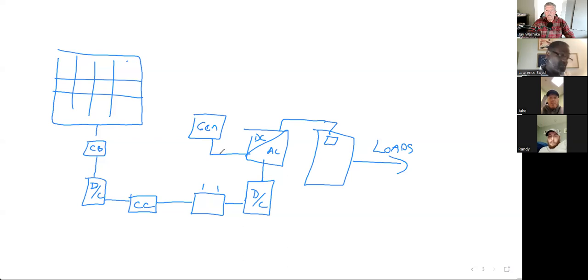Very common, very normal. You don't have to have the generator in this case, but a lot of people do, if it's your only home. Now, what I wanted to reinforce, other than walking through all the different parts, is when I turn on a load, how does the power flow? If I draw a line halfway through the battery, the solar array is going to push power into the battery. The only purpose of the solar array is to recharge the battery, or store the energy.